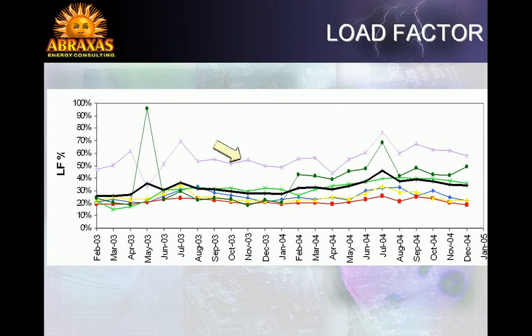An energy manager in charge of this project would want to investigate what building operational behavior is contributing to the low load factor values, and consequently the relatively high demand at some schools, and consider whether the demand could be decreased. The energy manager would also want to investigate whether other schools with high load factors are turning off their equipment at night.